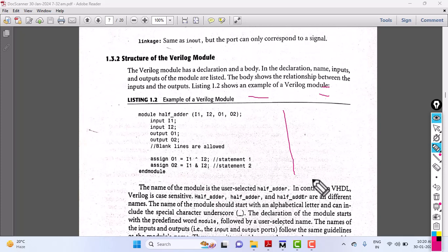I told you this I1, see, it can be 0 or it can be 1. I1 can also be multi-bit. It can be 3-bit, it can be 4-bit. If this is 3-bit, I2 also should be 3-bit. There cannot be random, non-uniform sizes. Ensure that I1 and I2 are of the same size. If you don't define anything here, by default it is 1-bit, which can be 0 or 1. So I am doing here I1 XOR I2, and assigning it to the left side, which is O1. This is what implements the sum of a half-adder. For the carry of a half-adder, it is an AND operation.